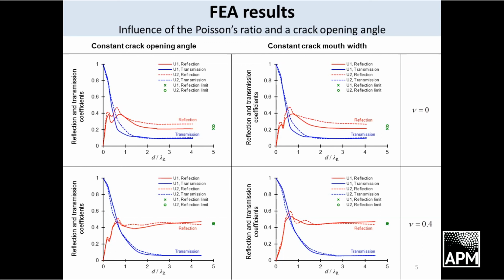Yet this idealization of a crack is only meaningful when concerning numerical simulations, because large angles of inclination will distort the finite element mesh and may potentially give inaccurate results. In all other senses, as you can see from these figures, there is no difference between the two cases, whether you fix a crack opening angle or a crack mouth width. So in both cases, you will obtain pretty similar results.